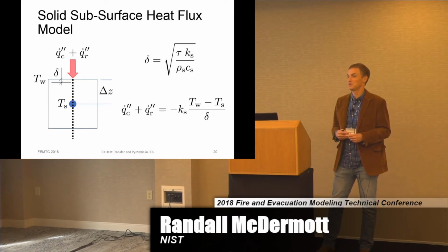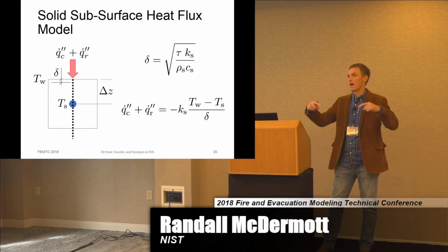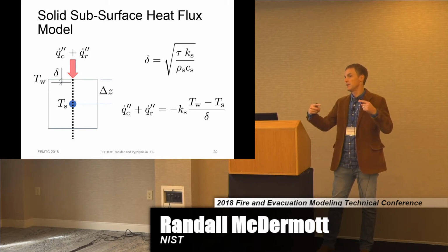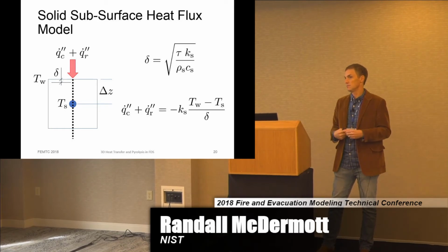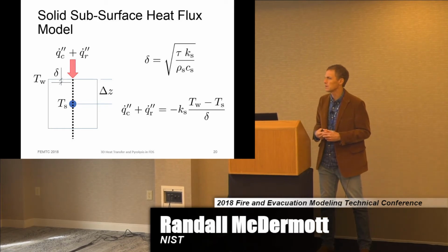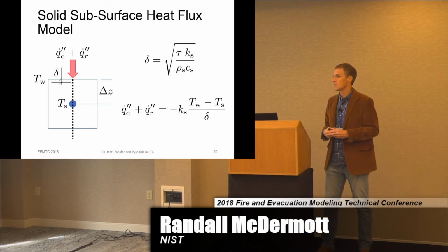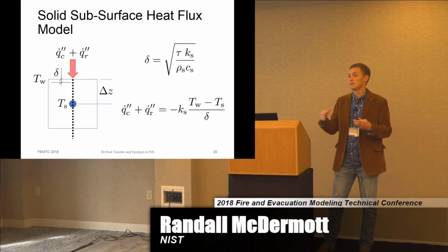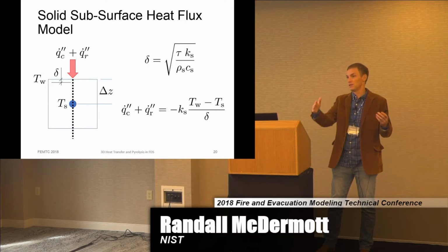Yeah. And then I had kind of a technical question on how you assemble the surfaces. You showed the HT3D surface type. Like on that beam example, have you applied that to multiple surfaces, or do you just specify it on one surface? In that beam example, it's all around the I-beam. It's just on that I-beam other than the patch, yeah. Okay. Which one were you talking about? Well, it had a constant temperature patch, and then the rest of that was just a verification case. And in that case, it was adiabatic and then a constant temperature patch for the boundary conditions.